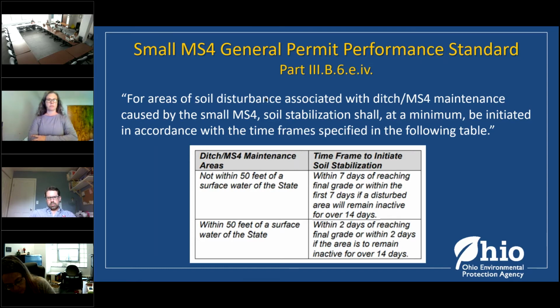And you would be required, if the site reaches final grade or if the site is going to be disturbed but a portion of it is inactive for a period of time, to implement some type of temporary or permanent soil stabilization. We want to keep the dirt on the site and out of our waterways, for water quality purposes, as well as the other social and economic benefits that can be obtained from that.